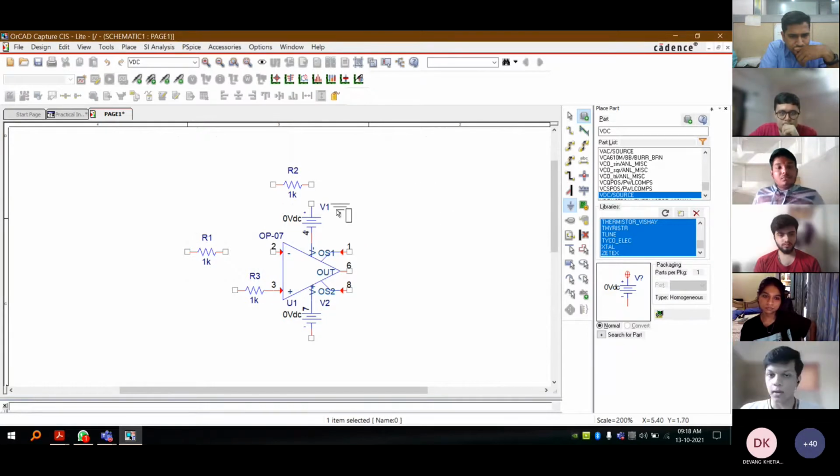Now, I clearly can't place this here directly. So what I'm going to do is rotate this component. Similar to LTspice, you can just press R here, or maybe in LTspice it's Control R. I can just press R here, place one up here on the VCC, place one down here on the VEE. So there we go. That's our ground up.